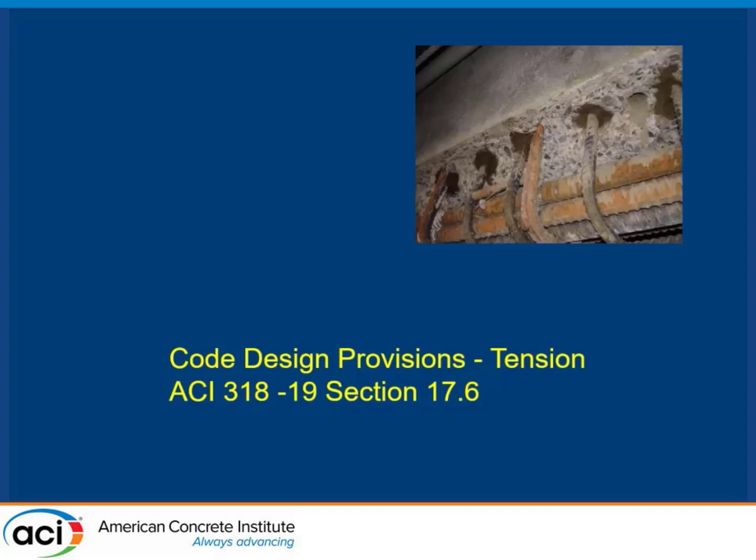And so that is the next big thing coming along, epoxying reinforcing steel into concrete, to develop it basically to transfer stresses, whether it be shear transfer or the continuation. My longitudinal steel busted, and so I'm really going to count on this thing now as my longitudinal steel, or something like that, right? You could probably expand on what we already know to use that product, but it was not official and there were caveats, but now that will be in the code.